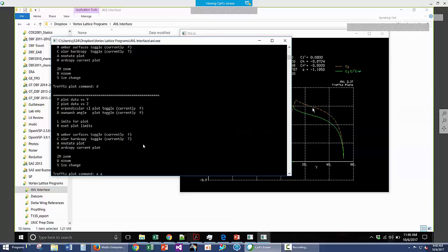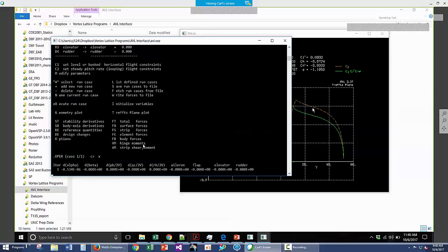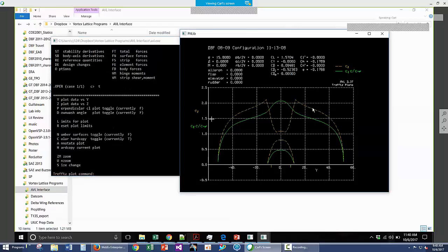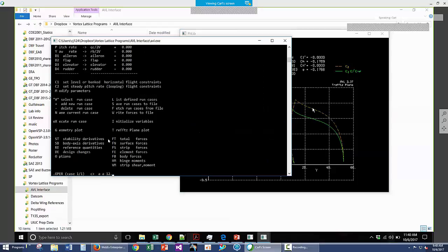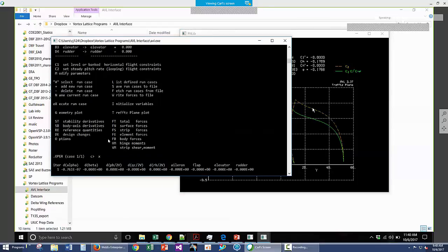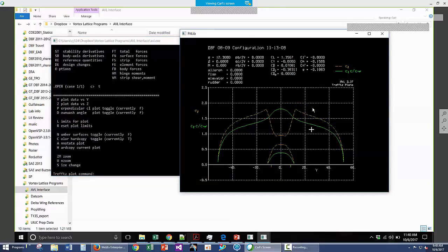Right, so let's go through and change the angle of attack to 15 degrees and look at the same results. And we said 1.7, that's right here. This whole region is stalled. Therefore, we can't actually get a CL of 1.57 for my airplane for this particular geometry. Is that useful, so I know that it's typically important to understand where the stall begins? Yes, and we'll talk about that too.